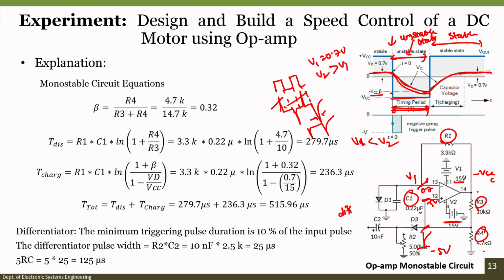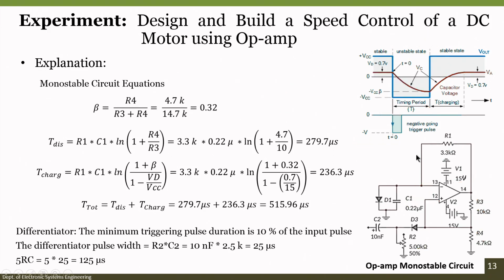How do we design it? In this case, we have to design the same pulse, but its duration should be smaller than 430 microseconds, and the complete cycle should be lesser than 0.630 millisecond, or 630 microseconds.